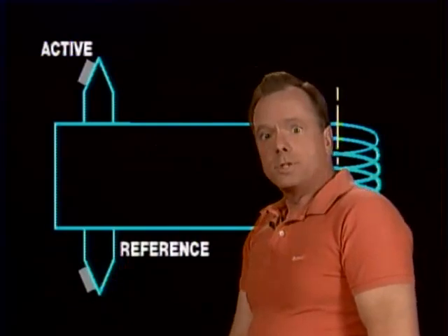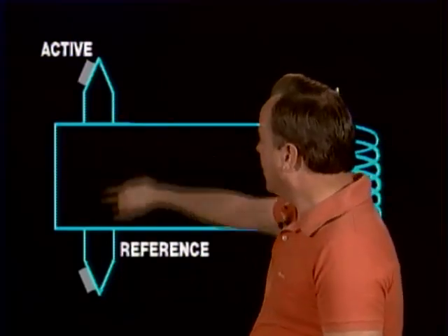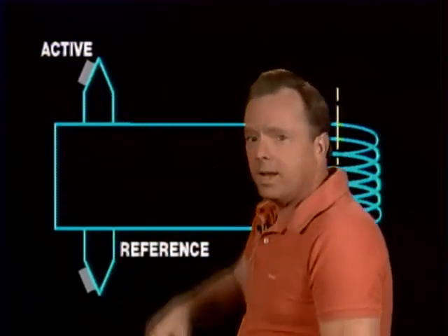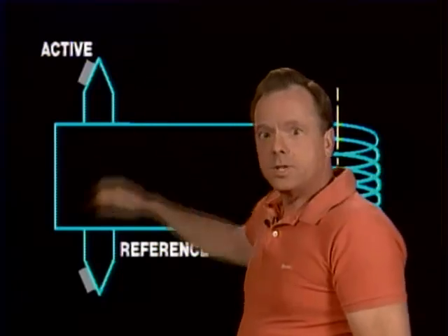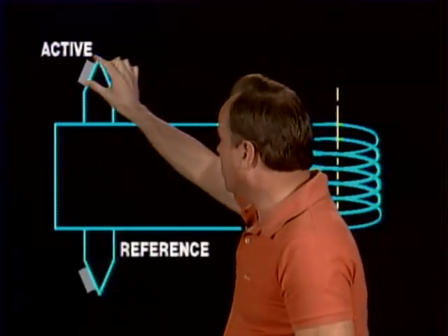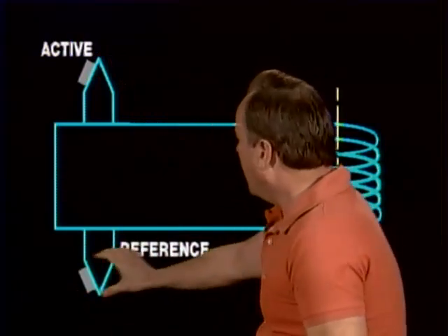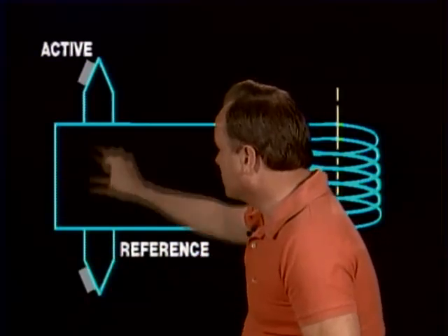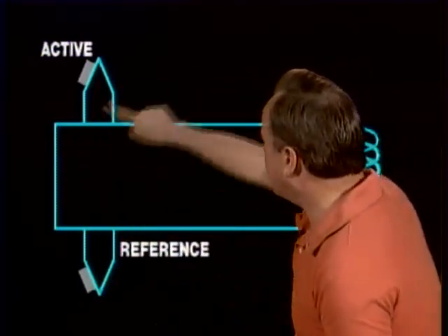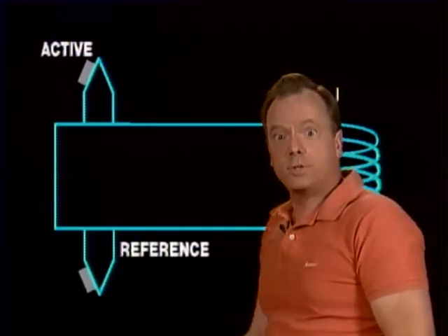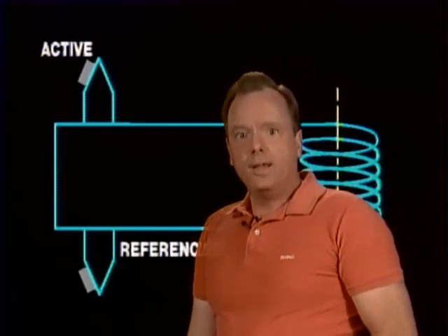Now, the way a thermocouple system works is you have two junctions of dissimilar metals. You'll have a hot junction and a cold junction. The hot junction will be located on whatever you want to measure. The cylinder head temperature will be located right on the cylinder. The exhaust gas temperature located right somewhere in the exhaust system. And then the reference indicator will be located generally near the gauge somewhere, the reference junction, I should say. Then the gauge measures the current generated by the difference in the temperature of these two junctions, and the gauge that measures that current is called a galvanometer.